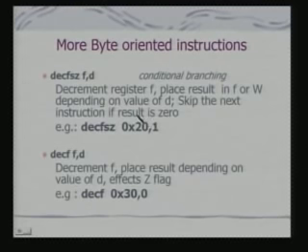Another interesting thing that happens is that when this result is 0, the PIC has to skip the next instruction. And if you remember the way the PIC instructions are executed, I told you in the last class that while an instruction is being executed, the next instruction is fetched. Now, in this case what happens?